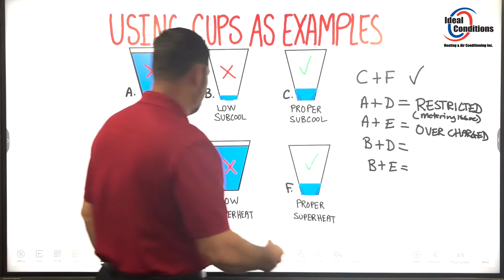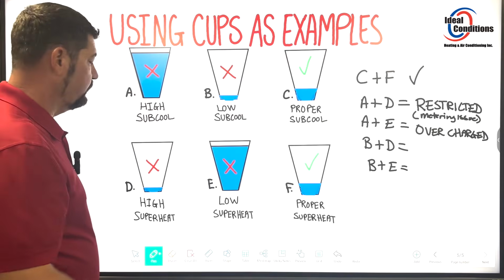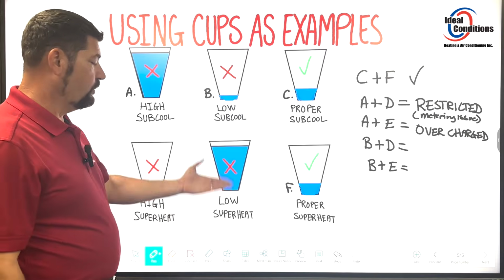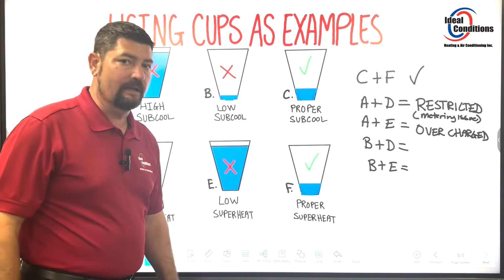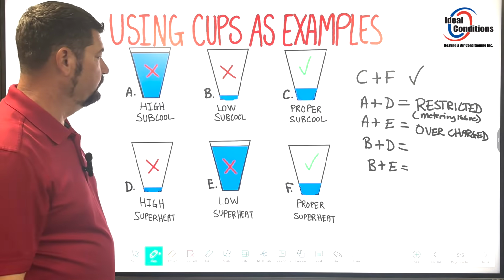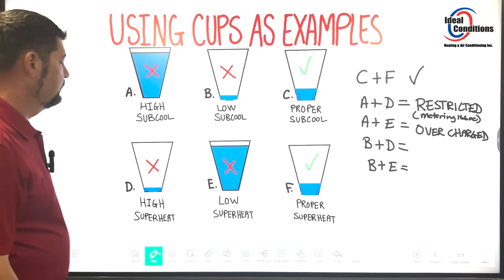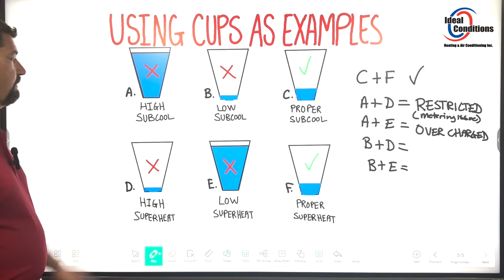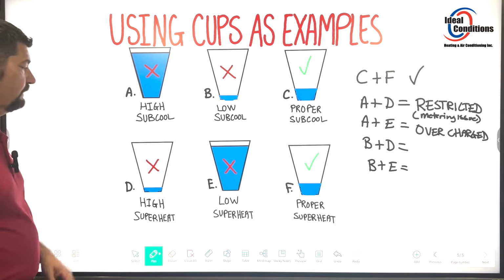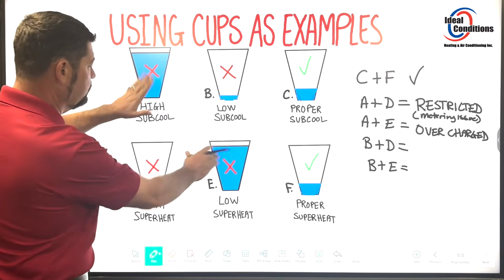And so that's not airflow related or anything like that. Could airflow cause me to have a low superheat? Yes, it can. Absolutely. But if that's the case, I'm not going to have a high subcool. So what we're talking about is the combination of these two things.